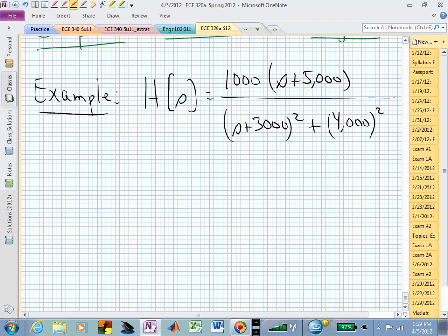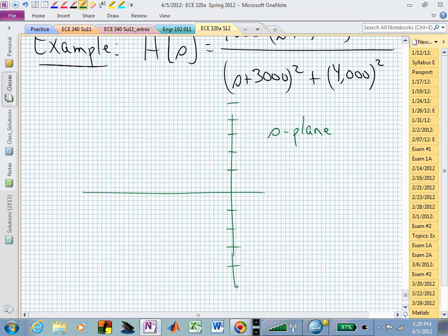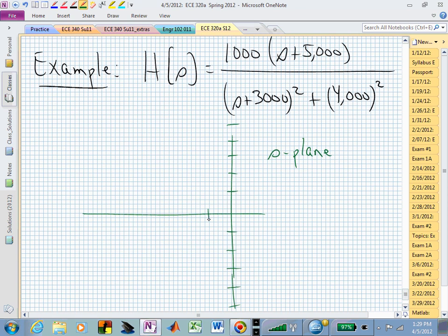Meaning, if we now want to sketch the S-plane plot of this, you may want to be more accurate because you have to have the same scaling on your horizontal axis as your vertical axis if you want your angles to be correct. So it's critical that your scaling is accurate if you're trying to physically get angles from this picture.